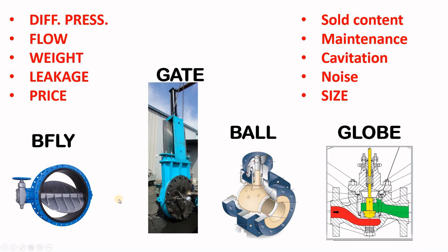If you look at the weight and the price, the butterfly valves are cheaper, especially if you go into a bigger size. When you are talking about 1 inch, 2 inch, 3, 4 inch maybe, we go to a globe valve. When you go above that, let's say 12 inches, 24 inches and more, we go to butterfly because of the price difference. Let's look at another thing.